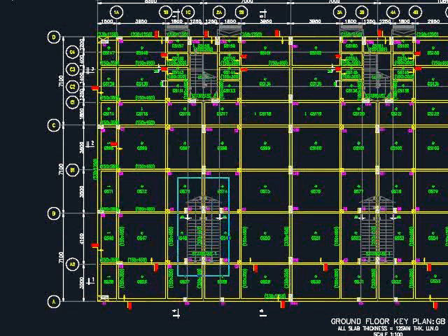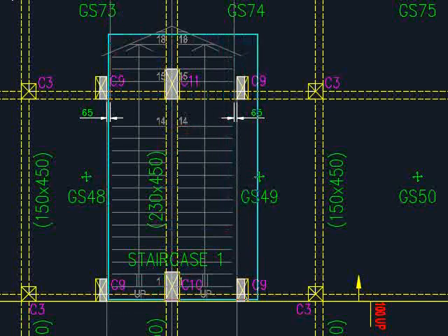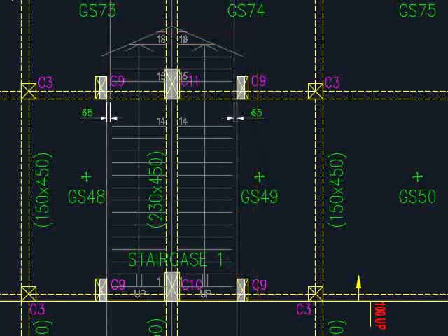You need to indicate the locations of the staircase so that the contractor knows they need to provide room for the reinforcement bar between the connections between the staircase and the slabs. Normally, the details of the staircase are provided, including the directions of the flow, whether it is going up or going down. You can copy this from the architectural drawing and impose it onto your key plan.